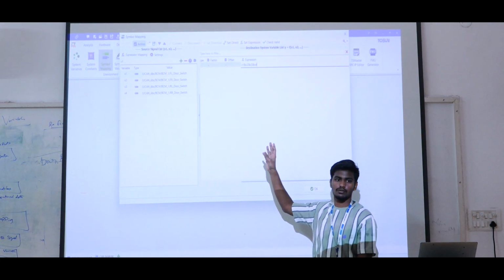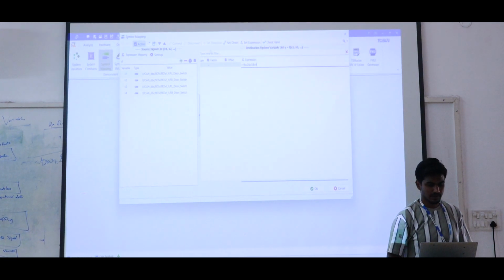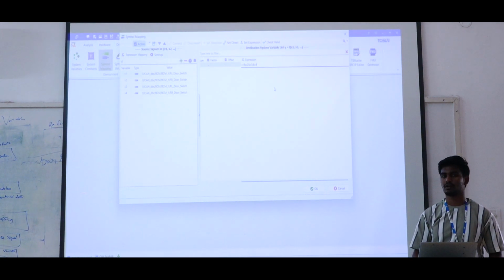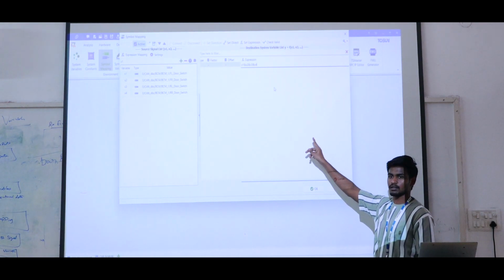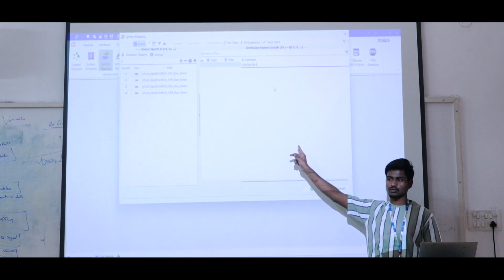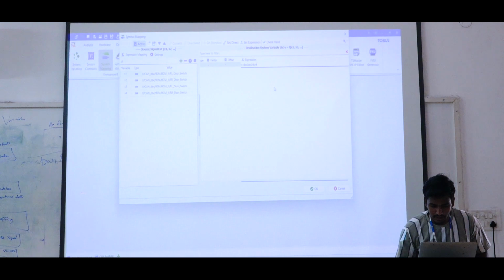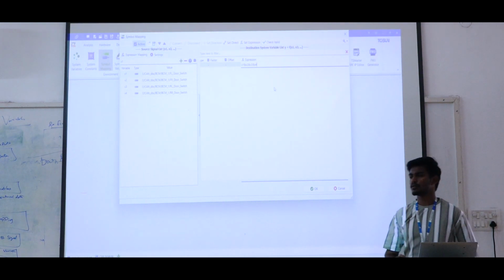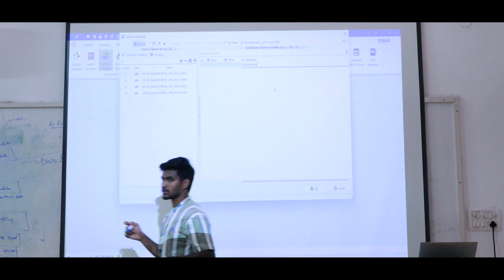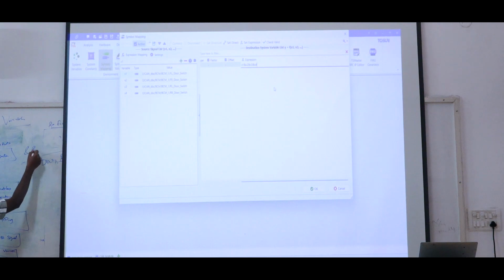Manually you need to type it using the small x. So what's the variable name they are having? The small x you have to type: x1 AND x2 AND x3 AND x4. So in our C program we use a double AND for logic, but here it is not like that, we are using only a single AND.